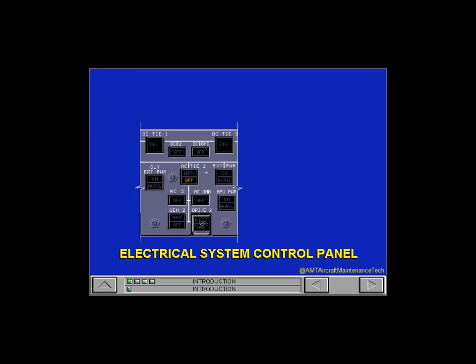The off light comes on when the system select switch is in the manual mode and the AC tie switch is set to off. The only procedure to reset the off light is to push the AC tie switch light while the system is in the manual mode of operation. Thus, you must first put the system into the manual mode.